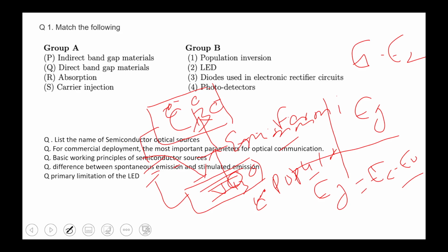When some light is focused on my photo detector, what happens in this case? Sir, it consumes light energy and converts it into electrical energy. No, it will also generate the electron hole pair, but in this case recombination will not happen. Recombination will happen only in case of defects.